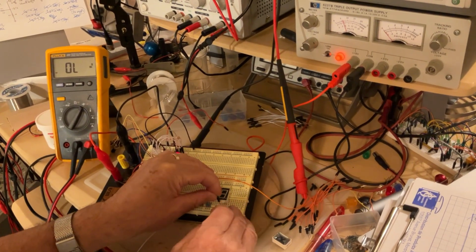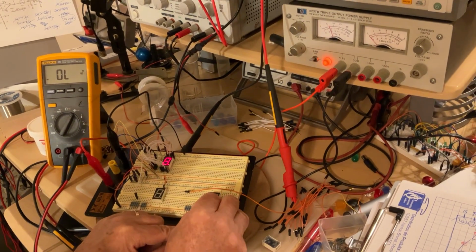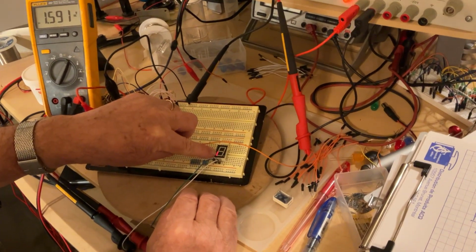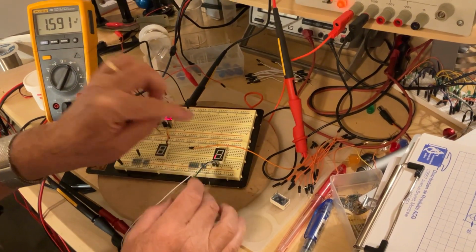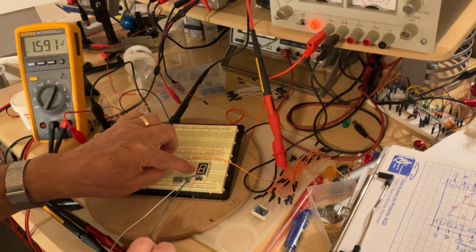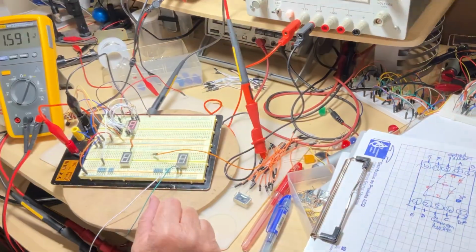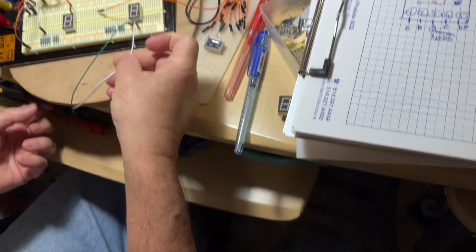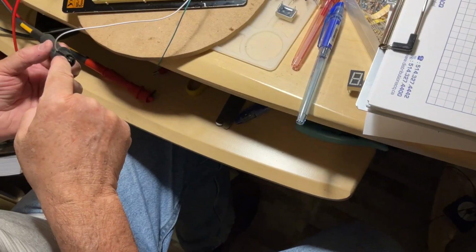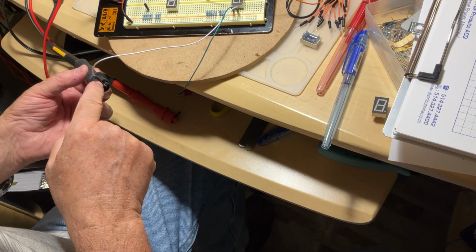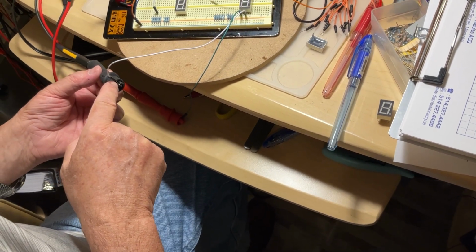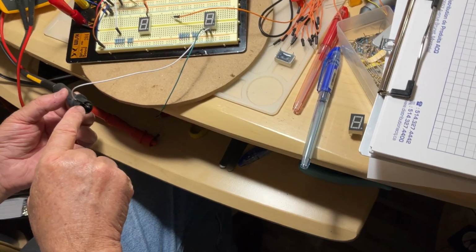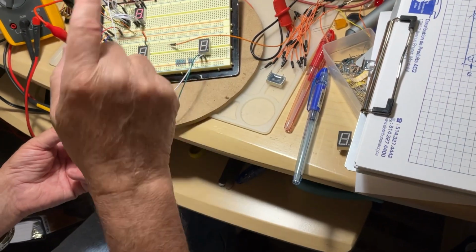Then I try the opposite way. This one here and that one here. I can see some light already. So this is the good arrangement for that kind of digit. Okay? So now I know this is my common, and this is going to the black of the meter. So the black of the meter represents what? It represents the negative. The negative is associated on a diode to the cathode. So this kind of digit is a common cathode arrangement.